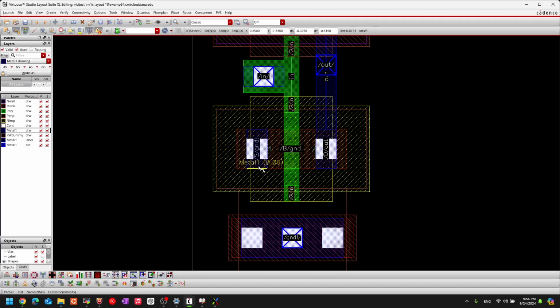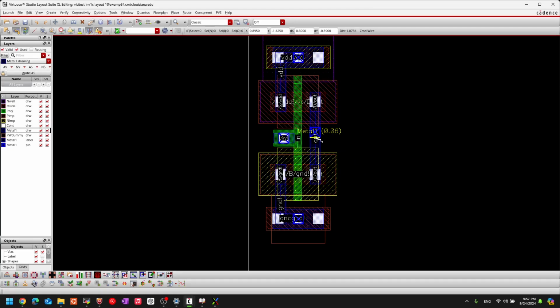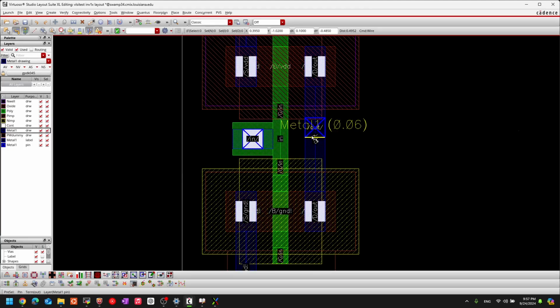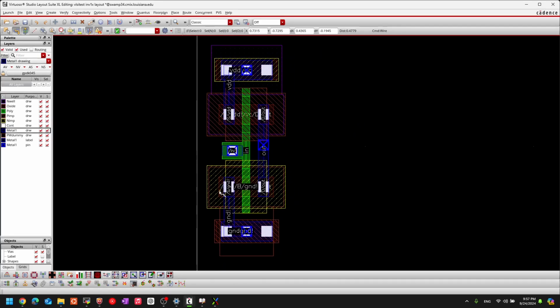And press on P for wiring mode, and then this will automatically come here, and then double click to place this wire to connect ground to source. Come here for the same procedure. We'll go for VDD source terminal to VDD rail. Double click. Now I connected these. All right. Looks perfect. Now, it does seem to look perfect, but we'll have violations.